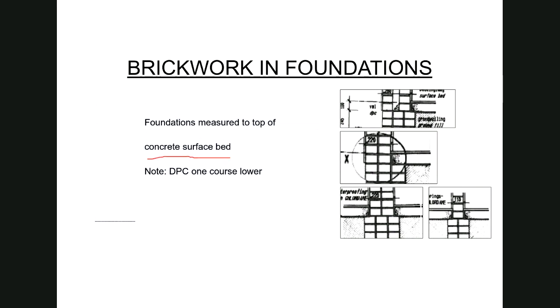And I put a note over there to say that please realize that the DPC course is one course down. So if I illustrate, you'll see to the right-hand side over here, I have pasted details 1, 2, 3, and 4. So for the first detail that goes through the cavity wall, the DPC line is like that. It slopes down and it comes out the other side. So what we have chosen then as our cutoff point between superstructure and foundations is top of concrete, which is the red line as I am indicating over there.